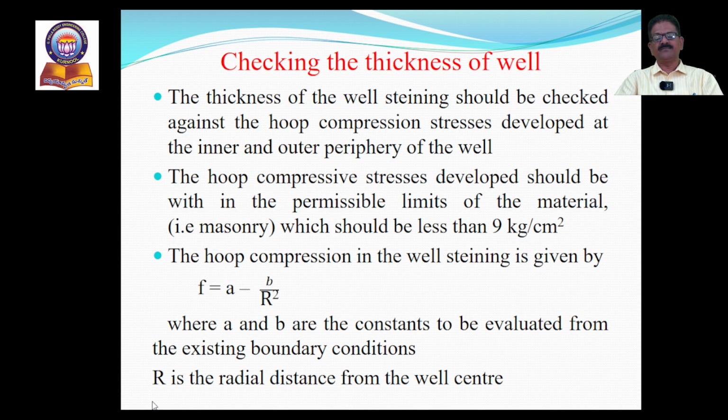The thickness of the well steining should be checked against the hoop compression stresses developed at the inner and outer periphery of the well. So we have to check at both surfaces, the inner surface and the outer surface of the well steining.